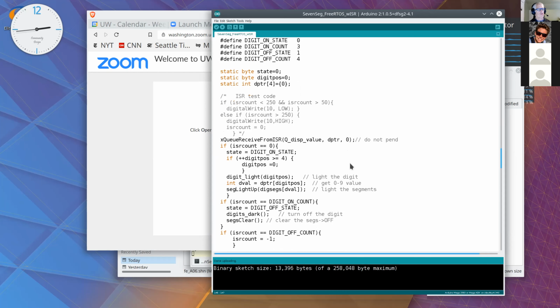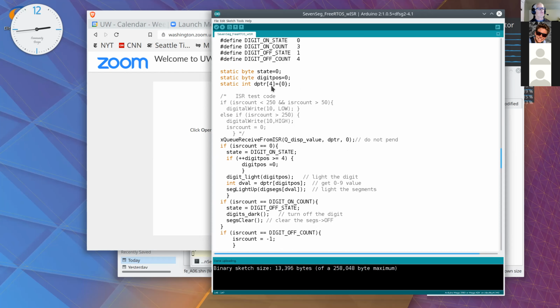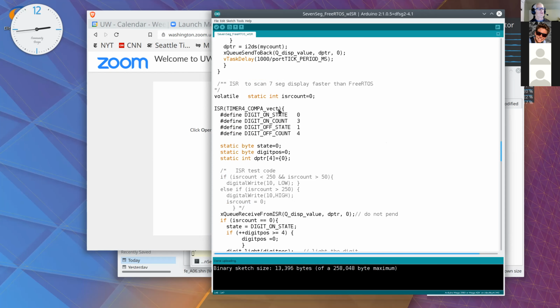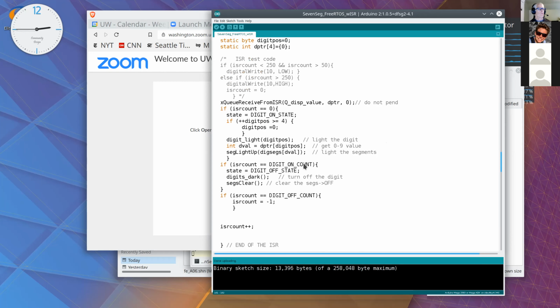So we put this into an ISR, and it keeps track of time in terms of how many ISRs have happened, and we can play around with a subtick, right? Because we could set this for 1 millisecond, and then these ticks will be milliseconds, but we can also change it. And that was another interesting thing I'll show you.